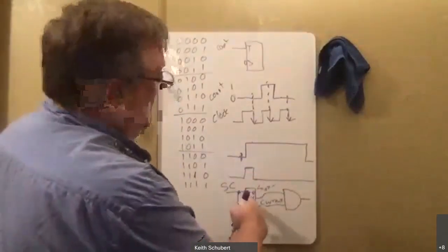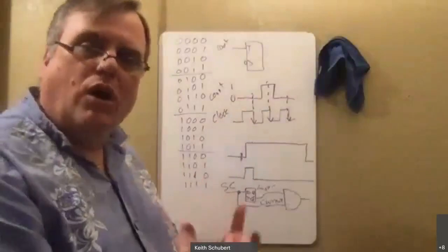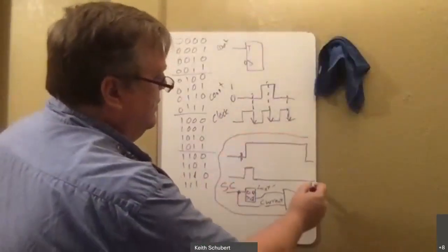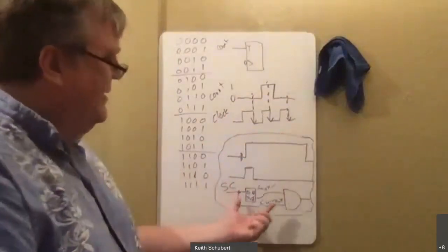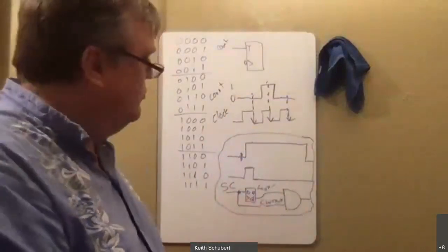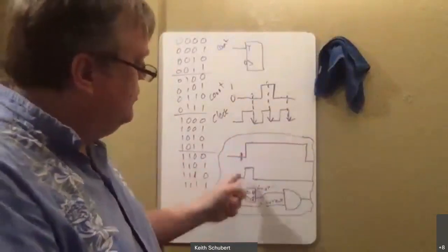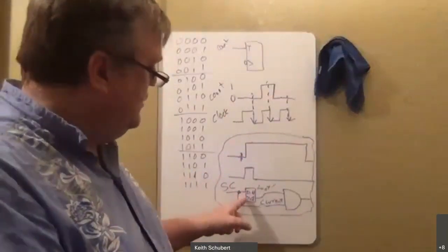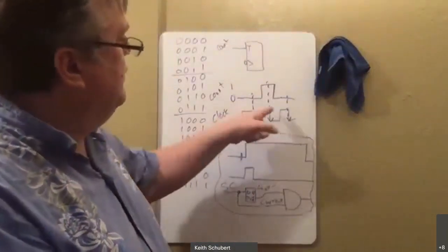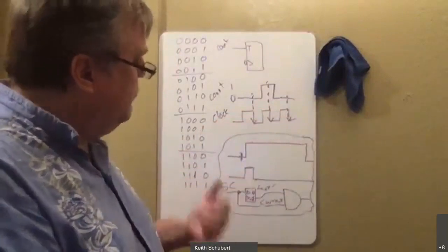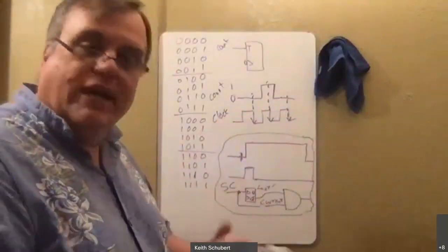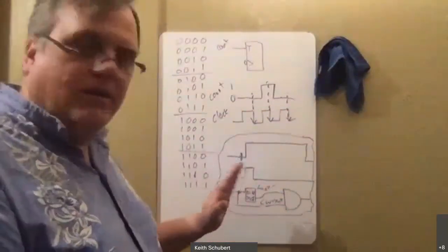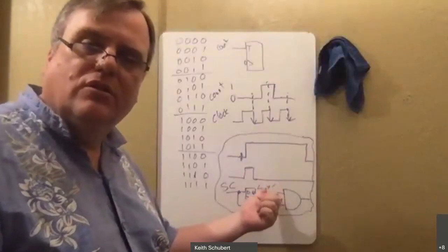And it's automatically clocked to be the right period, so you only get a 1 period pulse. The book doesn't mention this, but it's a simple enough circuit to kind of understand. As long as you've got a slow signal and you want to convert it to a smaller one, it's really easy to do it. And just make sure this clock is the same as whatever you're measuring on. Then the output will never be longer than 1 clock pulse, and you won't get clock run because of this, or counter run, I should say. All right, does this little side note make sense?